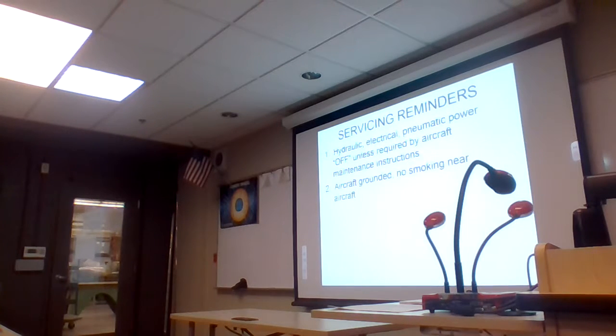Aircraft should be grounded, with no smoking near the aircraft. Common sense: most of the hydraulic fluids that we use for commercial aircraft are fire resistant, but why take a chance? We prefer not to induce anything that might happen, so no smoking, certainly around aircraft. And to guard against static discharge, the airplane should be grounded.